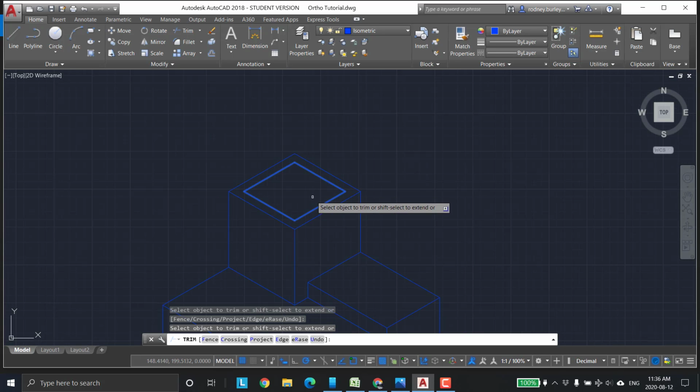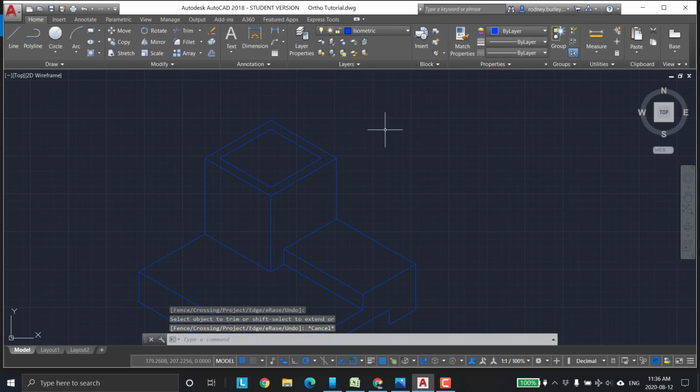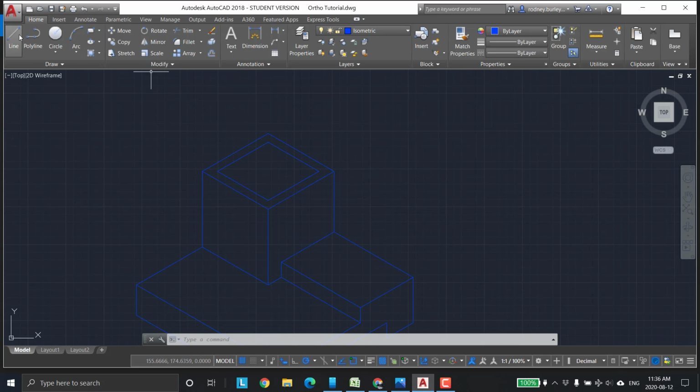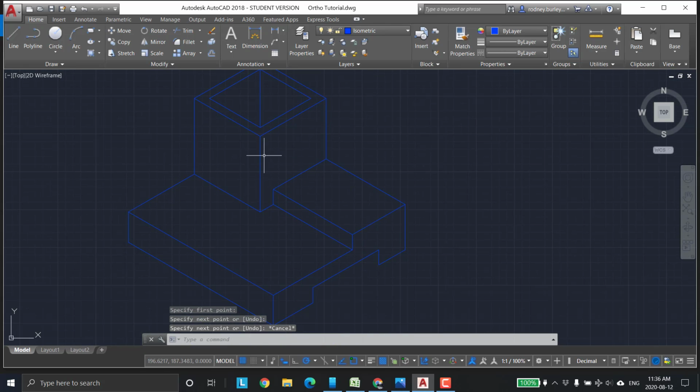Now there's another line you would see here, is you would see a line running down in here because this is an opening. And you would also see a line running across there because that's an opening. So we just simply go like this down, and that line would disappear right there. You wouldn't see it past that, right? You wouldn't even see the line because it'd be hidden there.